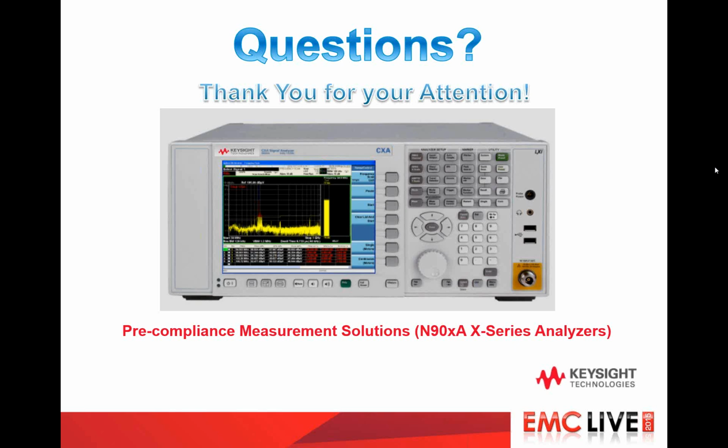Okay, here's another question. Do all spectrum analyzers come with a quasi-peak detector? No, typically a quasi-peak detector is optional within a product. And some of the older spectrum analyzers out there, whether it's the old HP ones or the Agilent Keysight spectrum analyzers, there are some older ones that do not have a quasi-peak detector available. So you need to check on your specific spectrum analyzer to see if it is available. Now our new series, our X series analyzer, it is available in all of our X series analyzers, and in those it just takes a license key to turn it on because it's already built in with our bank of detectors that we put in the product.